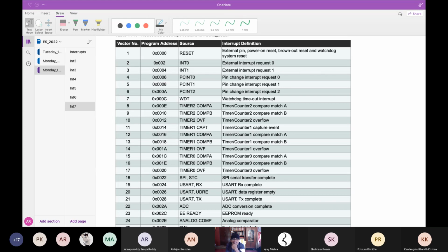Ajay Mishra: Sir, are you asking the memory size of flash in the ATmega32? No, the number of bits of the address, that's what I'm asking. Sir, it is 32K of memory in the ATmega32. True, but the program counter has how many bits? As I can see, there are 16 bits, but I don't know exactly. No, this is 14 bits. I told you to be very attentive in the last class. You read it, otherwise you are going to commit a lot of mistakes.